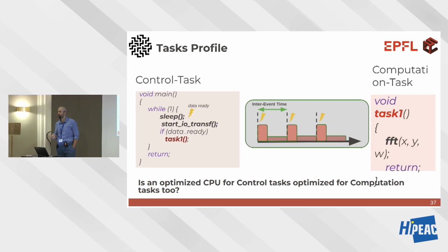And a DSP, an accelerator for FFT. So you will add accelerators or DSP extensions, or actually use a DSP CPU for doing the FFT.